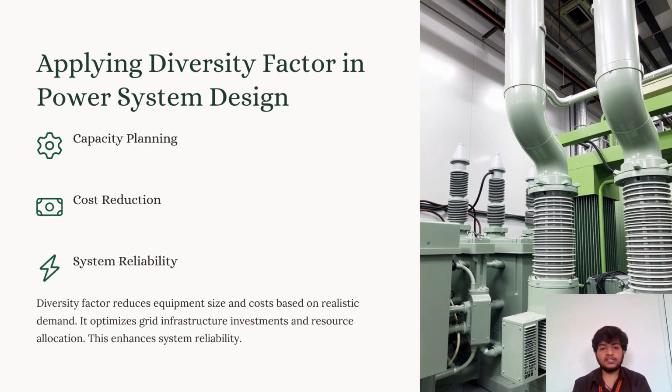By applying the diversity factor, we can reduce the cost, the system will be more reliable, and we can plan the capacity based on it. Diversity factor reduces the equipment size and the cost based on realistic demands. It optimizes grid infrastructure investments and resource allocation. This enhances the system reliability.